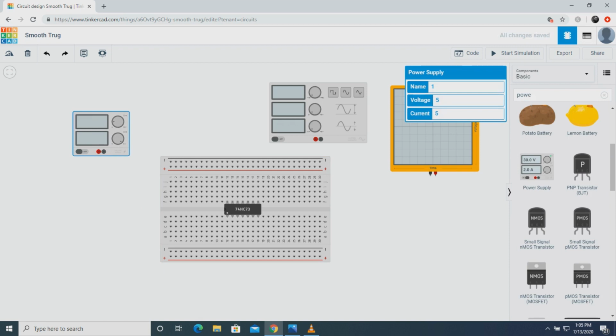What I did instead is put an Arduino. You can code everything here in the Arduino. I will just use that 5 volt supply from the Arduino. And to limit the current, because you know that each pin is rated for probably 5 to 10, 15 milliamperes to pass through, I will use a 1 kilo ohm resistance so that the current will be limited to 5 milliamperes. That way I can have a constant voltage and current supply. I actually don't recommend using this thing.